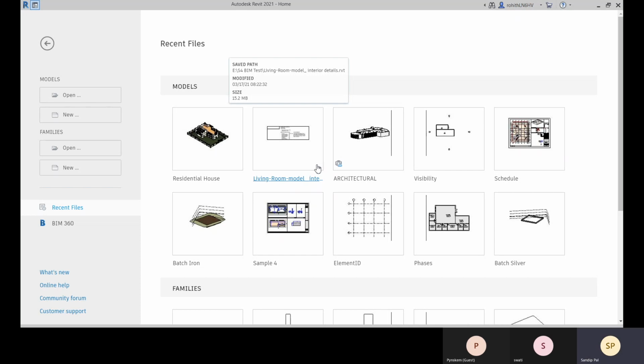All right. But it's not like a system family that you cannot create or model. It's kind of like a loadable family, kind of like a system family. Some features of loadable family and some features of system family are there in in-place family. Okay, so we have these